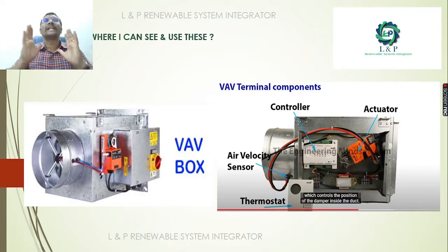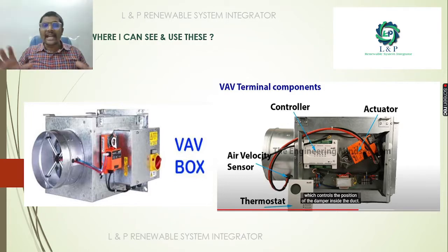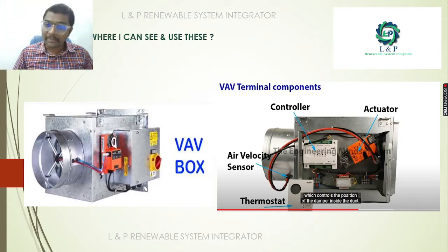Most importantly for the actuators, whenever we give a power supply and perform any sort of control operation, first you need to send a control signal and you should also receive a feedback. Only then can you identify its correct position. Once we program it, we link everything to the workstation through SCADA. In SCADA, if you want to know the exact position of these dampers, then we should have the feedback positions also.